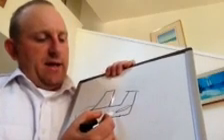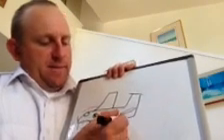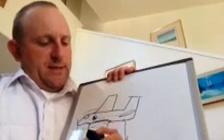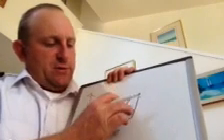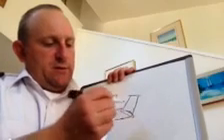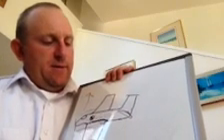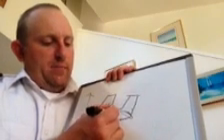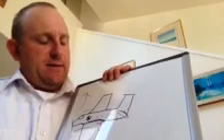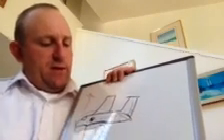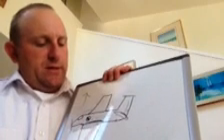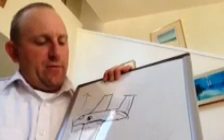That's creating a negative angle of attack that pulls the tail of the aircraft down, which rotates the nose up, and vice versa if we push the nose down. The stabilator is going to go like that. It's going to create a high angle of attack. That high angle of attack is going to generate lift, thus rotating the longitudinal axis about the lateral axis of the aircraft.